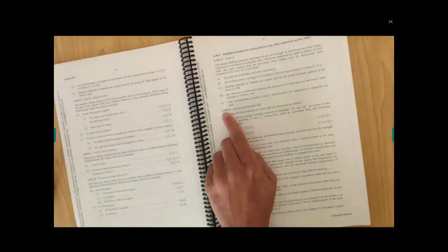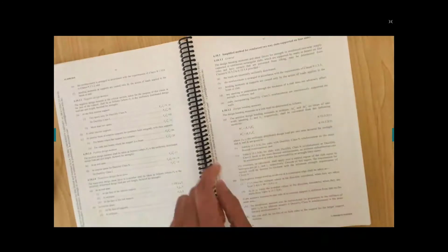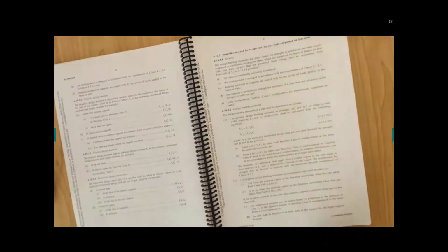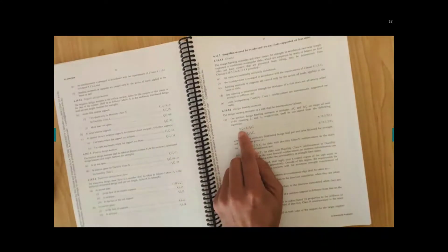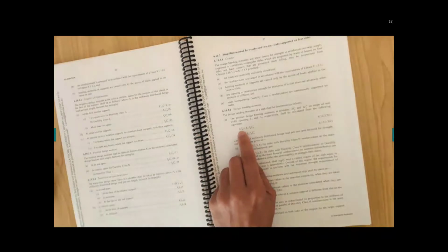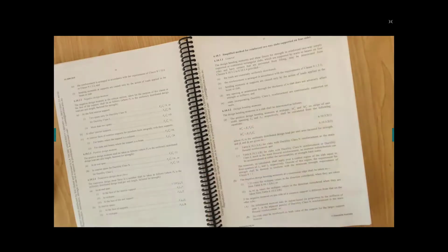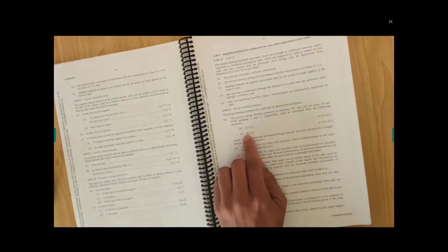Yeah, so here we have clause 6.10.3.2, which will allow us to calculate the positive bending moment, and there are negative design moments here as well. It says that mx*, where x is, you remember, the shorter span. The positive shorter span moment would be beta x, Fd, where Fd is 1.2g plus 1.5q, and Lx squared, and you already know Lx, right? Lx is the center to center distance. My* is equal to beta y Fd Lx squared.